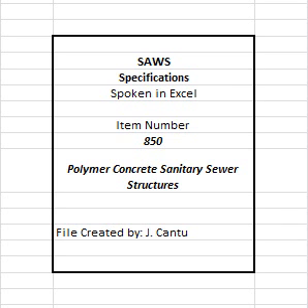3. Summary of criteria used in structure design including, as minimum, material properties, loading criteria, and dimensions. 4. Include certification from manufacturer that polymer concrete structure design meets or exceeds the load and strength requirements and are manufactured in accordance with ASTM C478, ASTM C857, and ASTM D6783, and when applicable reinforced in accordance with ACI 440.1 R15. 5. Submit calculations signed by a professional engineer registered in the state of Texas demonstrating the structures meets the design criteria established in plans. 6. Structures shop drawings shall be sealed by a licensed professional engineer registered in the state of Texas.